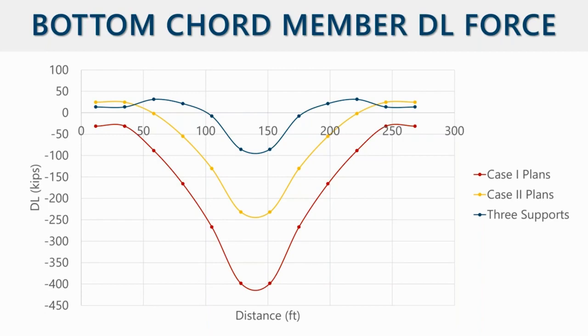Because in BrR, there is only one dead load case we use in the load rating. Okay. So if this is a one-time job, the first impression is that we can always load rate this bridge. We could say, okay, I'm just going to build 2 models, 1 model for dead load and 1 model for live load, and I'm going to pull out the results and do the load rating in a spreadsheet. Okay, that's a solution. But if this is a one-time job, that's okay. We can do it.